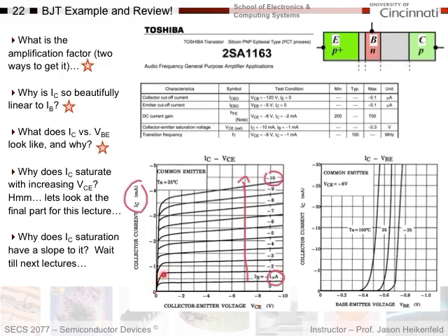So once I get to enough voltage to reverse bias it, the BJT doesn't operate more efficiently, and it just gives me constant output of collector current for a given base current. So you just basically get to reverse bias for the base collector, and then the BJT amplifies, and more reverse bias just puts more reverse bias on the base collector. But just like reverse saturation current for a diode, more reverse bias doesn't change the current. So this actually kind of looks like I naught, right? Insensitive to reverse bias voltage.